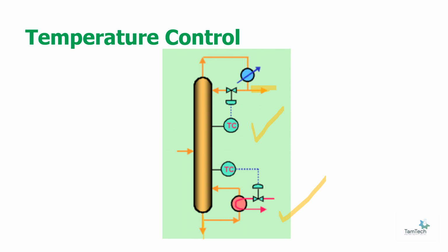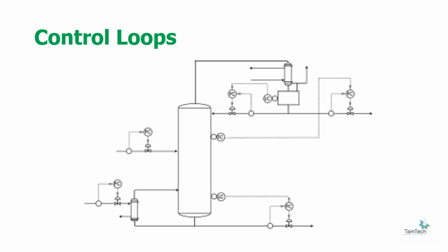Up to this point, we just discussed general temperature with compositions, some disturbance variables, pressure, flow rate, etc. But if you want to see some kind of control loops, we could have a look at this one. So for example, at the bottom, you have the level control going with the flow control. On the left, you have the flow control. Most probably it will be controlling the composition or temperature. It could also be the composition or temperature with the boil up ratio and so on.